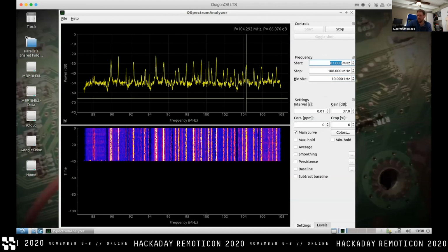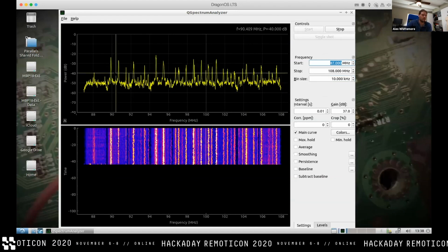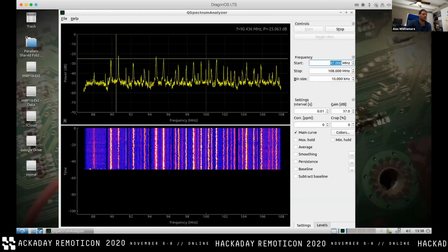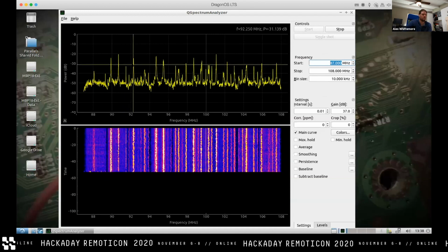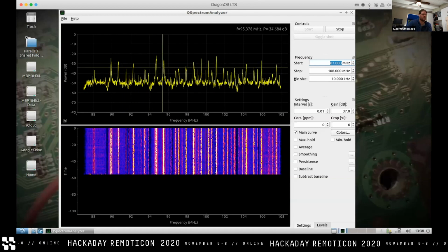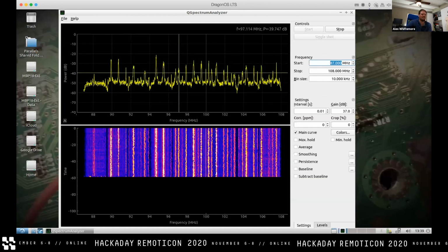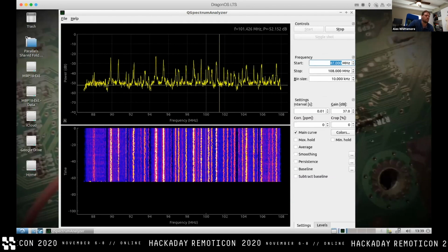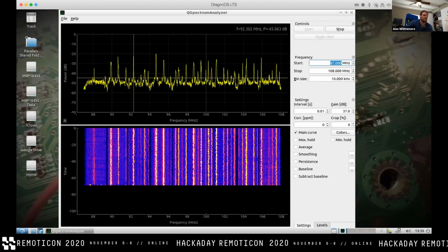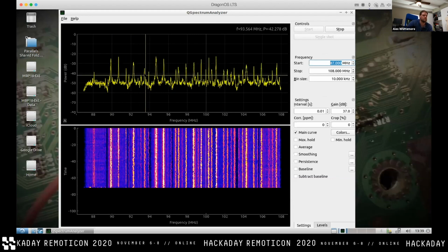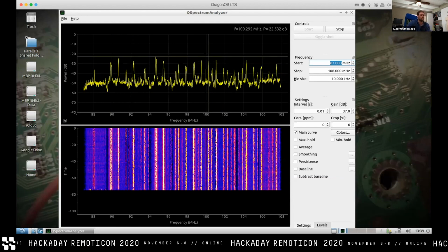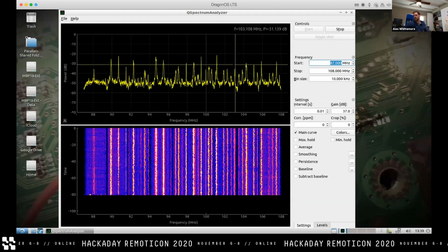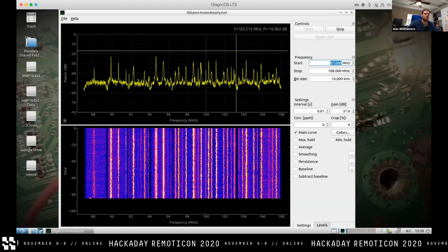On the flip side, what's cool is we see that all of these radio stations are totally coming right through. I count 1, 2, probably 3, 4, 5, 6, 7, 8, 9. I don't think so. I don't know how frequently the radio stations are actually spaced. I guess it's 0.3 megahertz. So all of these lower peaks are probably just weaker radio stations, but very clear that there are a bunch going on here. And this is effectively what we can do with our near field probe on our own board.